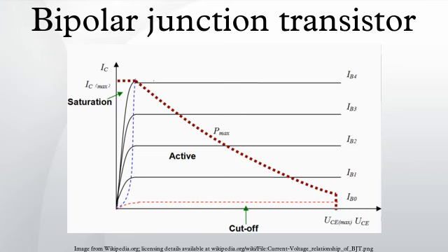The incidental low-performance BJTs inherent in CMOS ICs, however, are often utilized as band gap voltage reference, silicon band gap temperature sensor, and to handle electrostatic discharge. Germanium transistors. The germanium transistor was more common in the 1950s and 1960s. And while it exhibits a lower cutoff voltage, typically around 0.2 V, making it more suitable for some applications, it also has a greater tendency to exhibit thermal runaway.